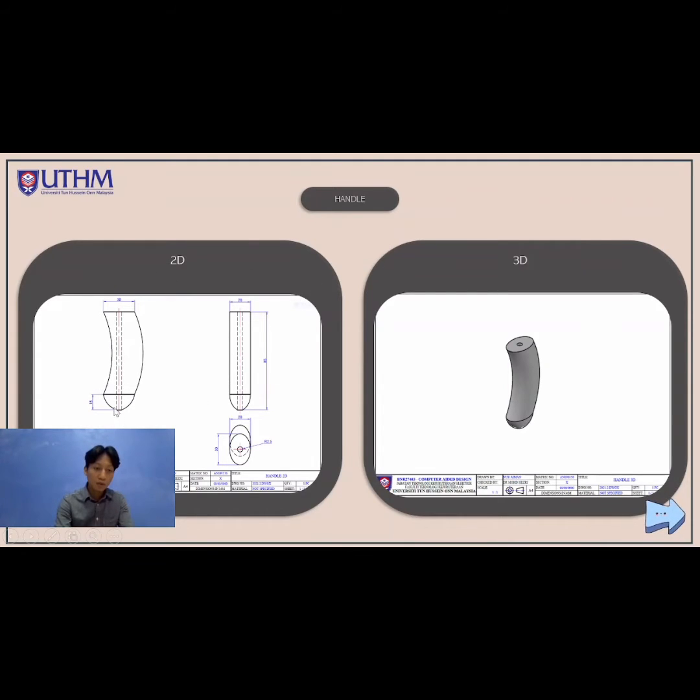And next we make this one. Next we make a straight line on the center of the ellipse using the line command with a length of 20 millimeters. And then using a move command, we move the center of the shape I made just now to the other center of the ellipse, to be connected to the line.